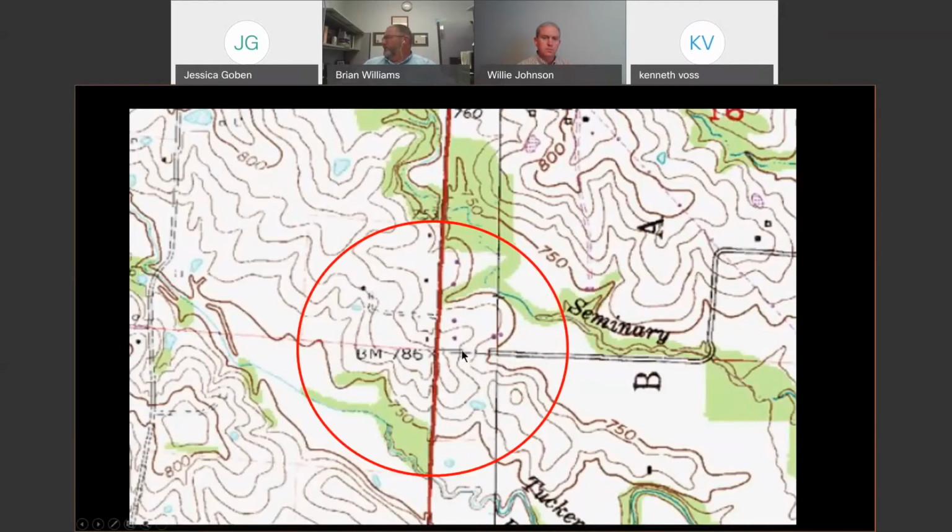So here's the topo of this area. Okay. So Route H moving this way. But anyway, as you can see, you've got field and drainage going this way, drainage going this way. Got some swales going this direction, so we've got drainage moving that direction, which is typical for an intersection project with some ditches in it.